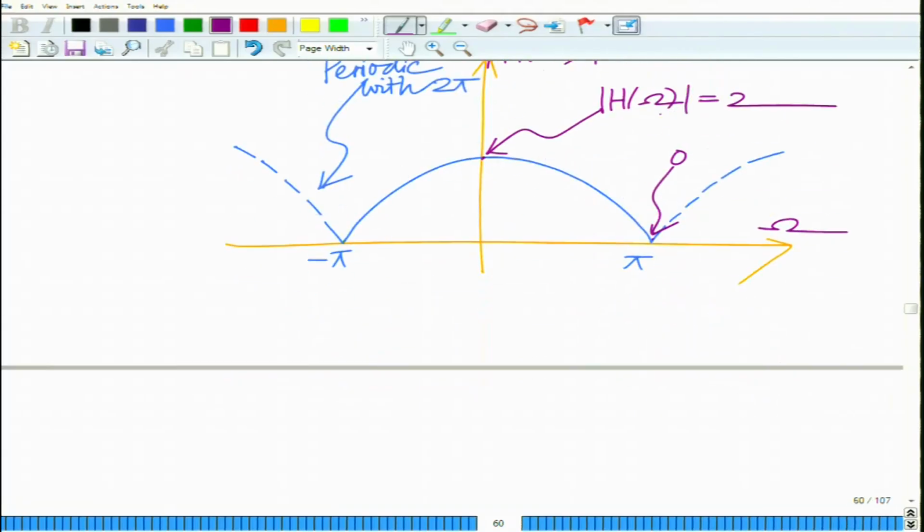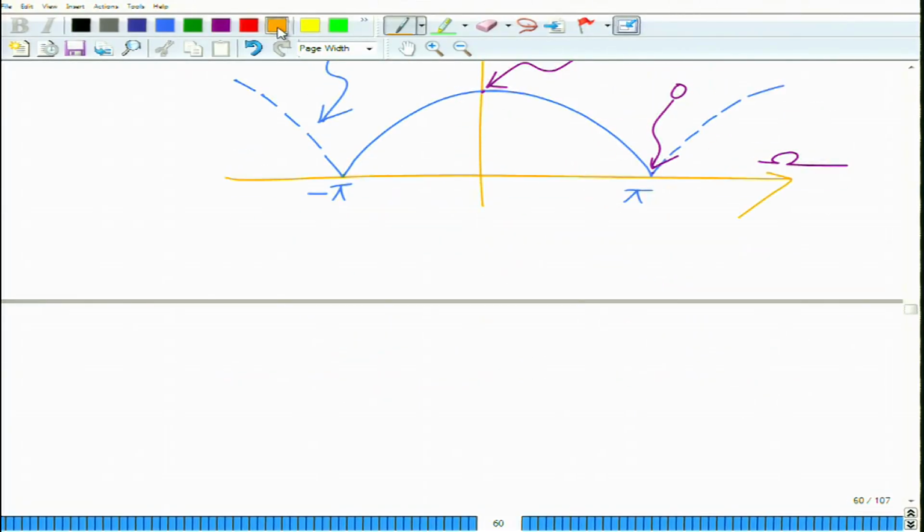So, clearly this is a low pass filter, but of course, it is not an ideal low pass filter, because it is not suppressing, that is the attenuation is not 0 outside of a cutoff frequency. And therefore, we know that for a non ideal low pass filter, we can characterize the effective bandwidth. One of the metrics to characterize the bandwidth is using the 3 dB frequency. Okay. So, first you can see that this is a non ideal discrete time low pass filter.